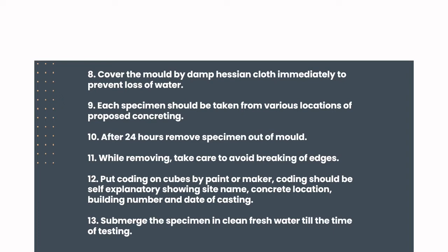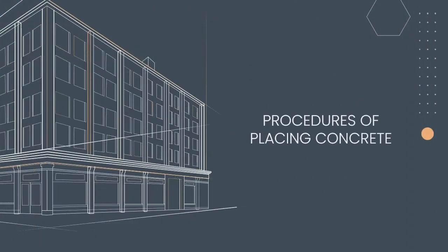The coding should be self-explanatory, showing the site name, concrete location, building number and date of casting. Thirteenth, submerge the specimen in clean fresh water until the time of testing. Here is the procedure of placing concrete.